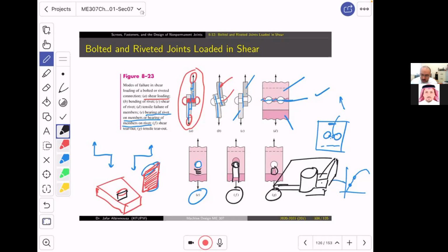There is an area in front of this, just like an area of stress concentration. And because there is no material in the end, that part becomes highly deformed, and it may reach the ultimate or failure stress, and that's why you have a tearing.